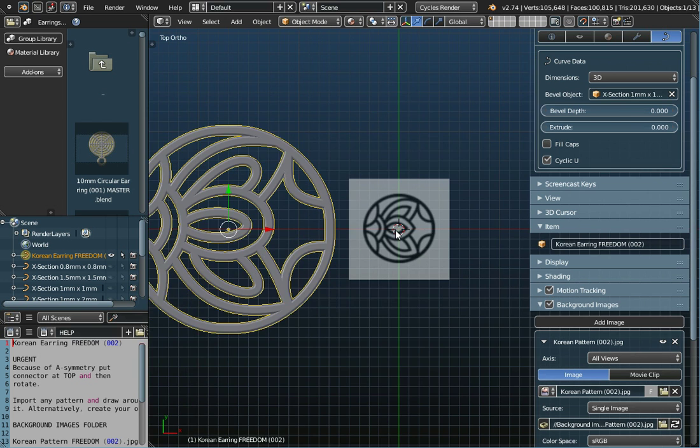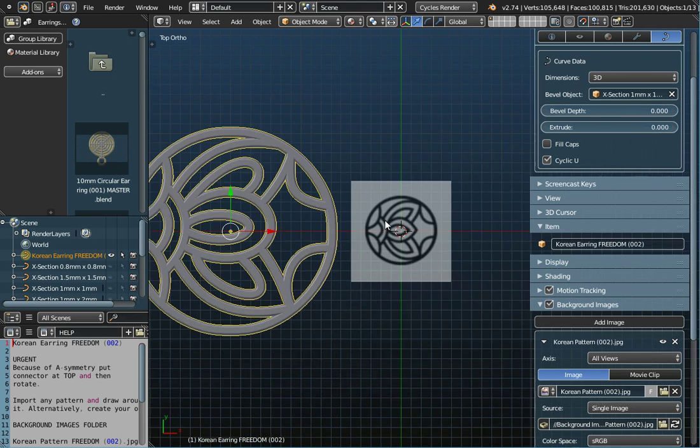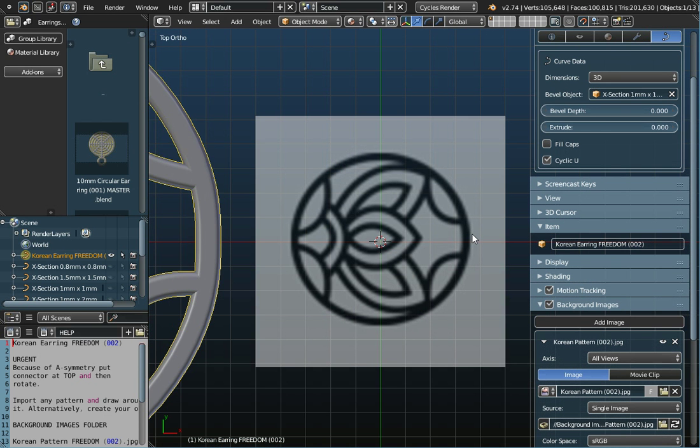So there's my image, which was actually created in Paint and then saved as a JPEG image. As you can see at the moment, the size of this is different from the size of my finished object. Before you create this, you need to resize this image. One of the important things in Fluid Designer, and in 3D printing, is the thickness of the finished object. You really want a minimum thickness of about 1 millimeter, and each of these blocks here is 1 millimeter square. If I drew around my image at the moment, I could create an object around it, but it would be too thin.